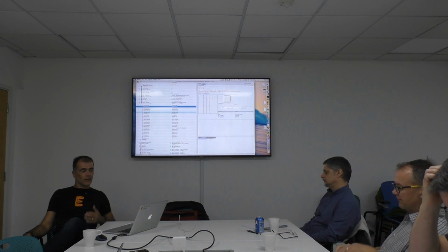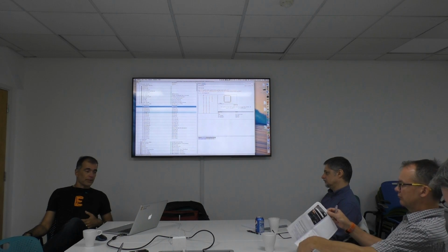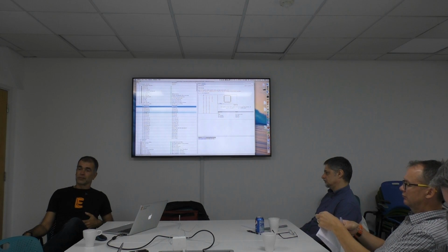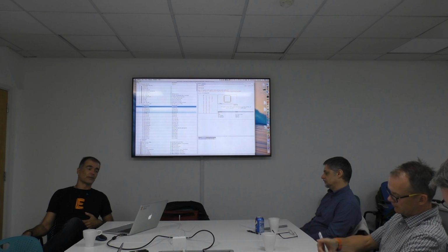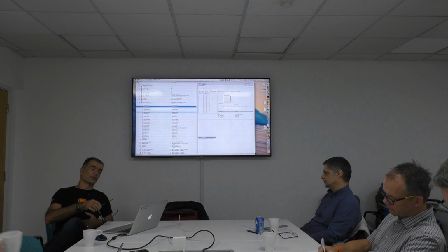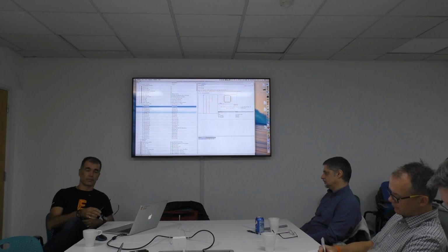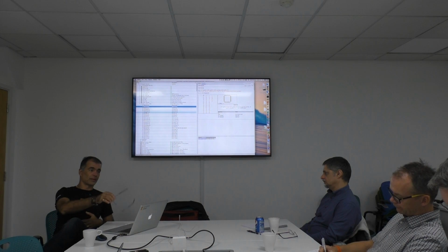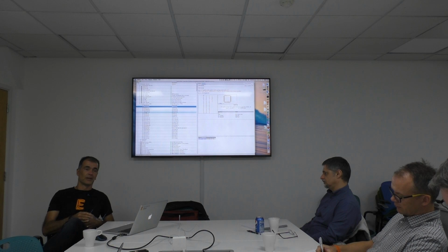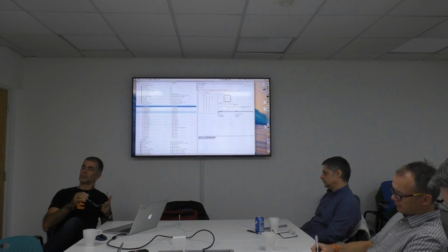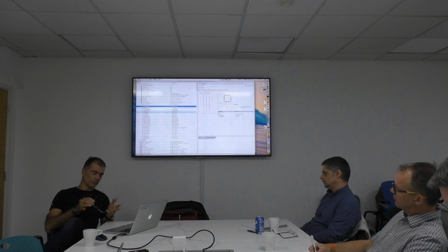That's something that's fundamental for the work. So in creating a library, you have to be very careful. Don't make the chaos I have done now in Fusion, because as soon as you have a component defined, it has a name, the symbol has a name, the package has a name, it comes from a library.